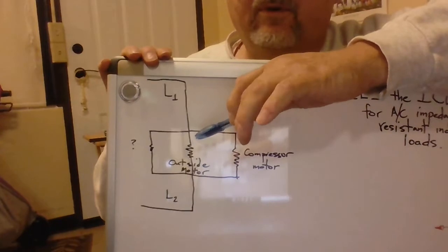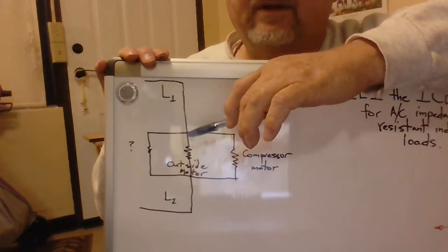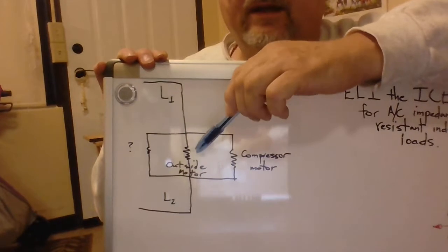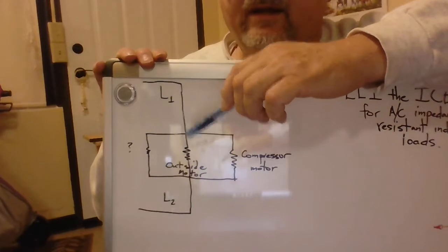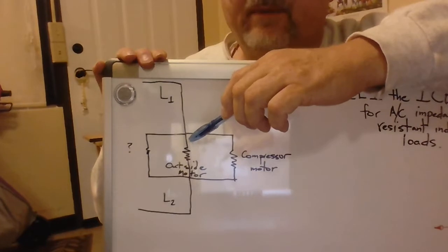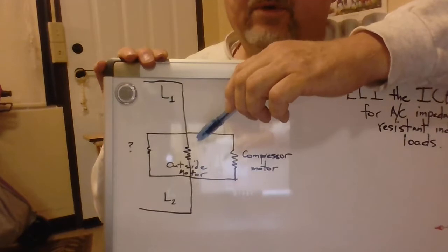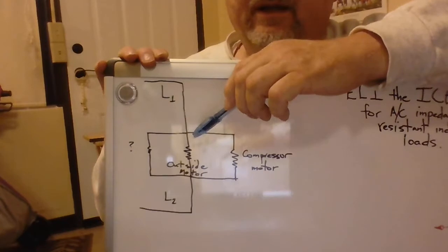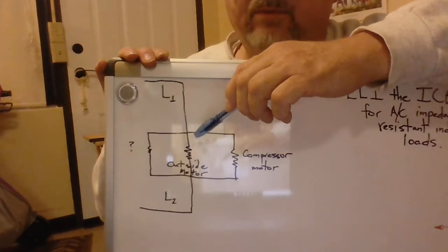And you've got to be careful. You've got to get the capacitor too, because you never ever want to replace a motor without a capacitor, and you really don't want to replace a capacitor once you spin the fan and it starts working. You know the capacitor's weak. You can check it with your voltmeter, but you know it's going to be weak. What in all likelihood happened is the motor caused damage to the capacitor. And if you just change the capacitor and not the motor, you'll be returning out there in 2 or 3 months to replace the motor, and the customer's going to be upset unless you put it on the ticket saying that you urged them to allow you to change the motor as well as the capacitor.